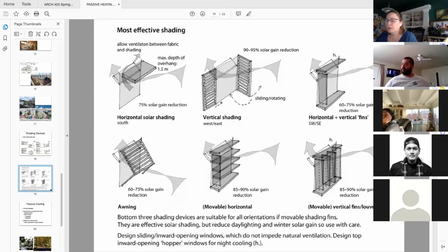In our climate in particular, and actually several, morning sun is more welcome because our spaces cool down overnight. So letting more heat in during the day is desirable. But then by afternoon, when temperatures heat up and that sun is going down and you get that really sharp direct west direct gain, a vertical fin on the west side of your glazing can help prevent some of that from coming in. You can do that in patterns. This one is also a movable one.